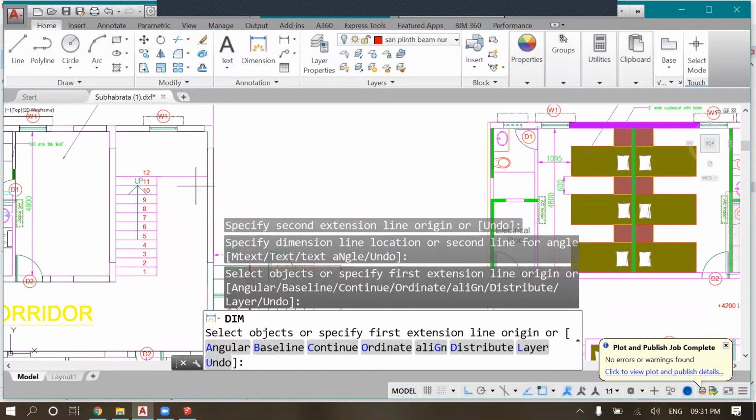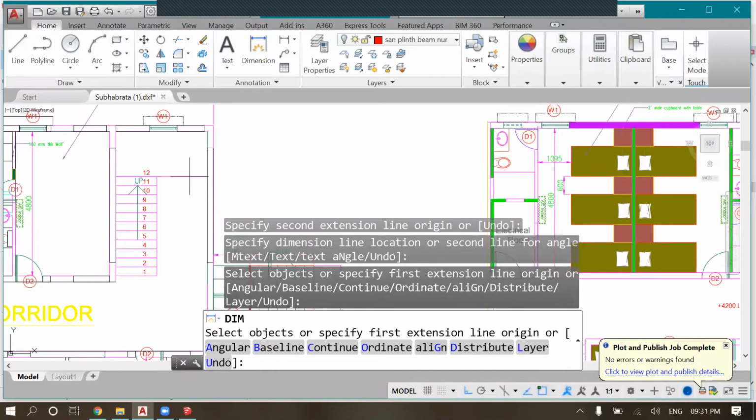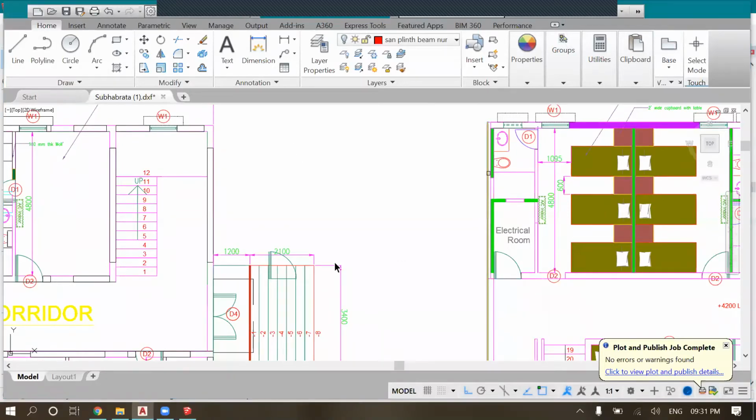Let's divide it. 3200 is our total height, divided by, and here we have 12 for this side, and we also have 12. Into one more. Yeah, it is around 169 if we take 20 stairs.